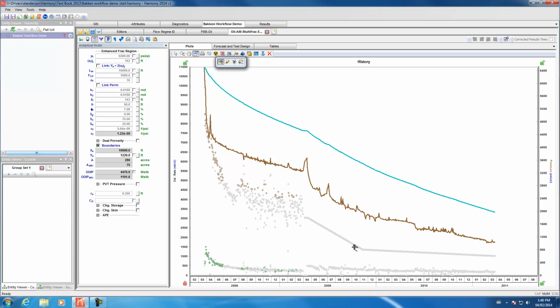I'm going to ignore all of this and just capture the region right around where we get our liquid level measurement, and then we'll catch some data at the end, and we'll try and make sure that all of this matches. I'm going to put a little bit of weighting on some of these data points at the beginning, a few in the middle, and a few at the end. And this will hopefully ensure that we can bring that simulated pressure response down.